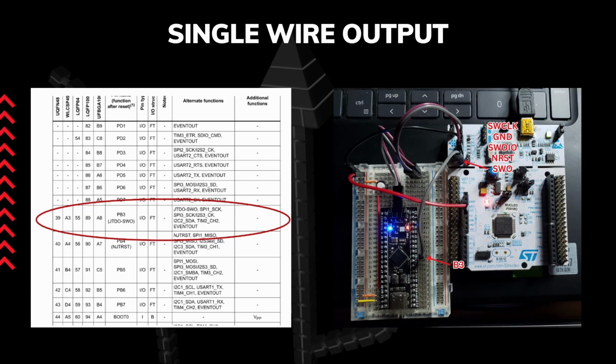Another debug feature we'll be using is the one for the microcontroller. The thing is, USB transfers must be processed very quickly and we won't be able to place a breakpoint and inspect program step by step. Instead, we will configure the microcontroller to send text messages to the IDE. The feature that does it is called Single Wire Output or SWO for short.